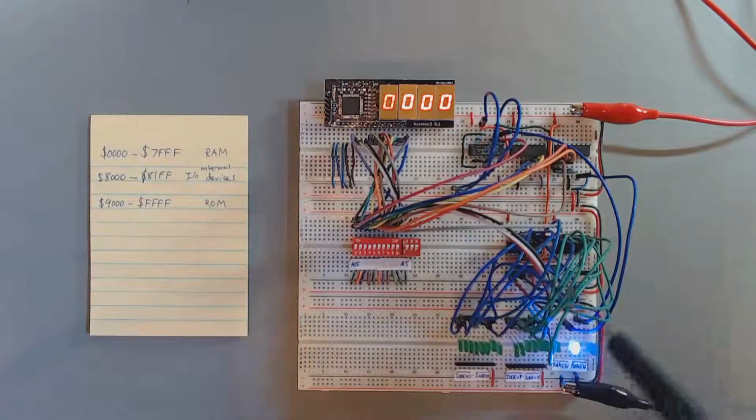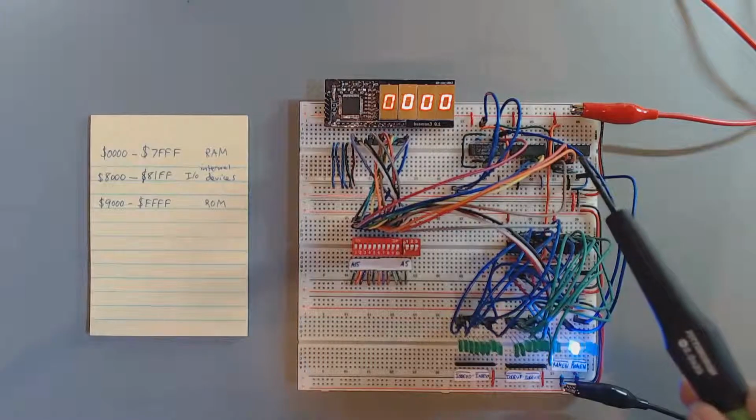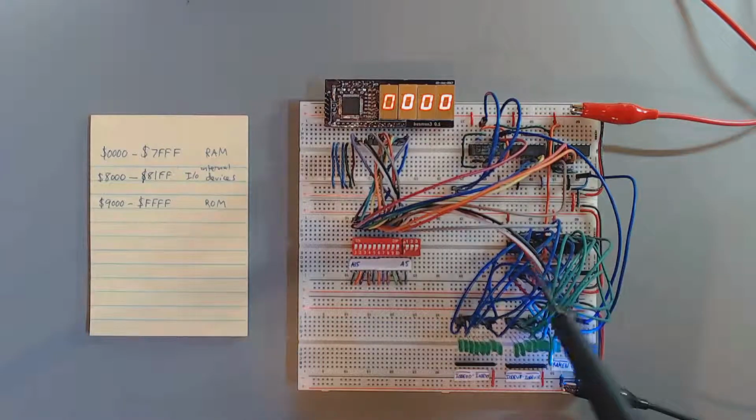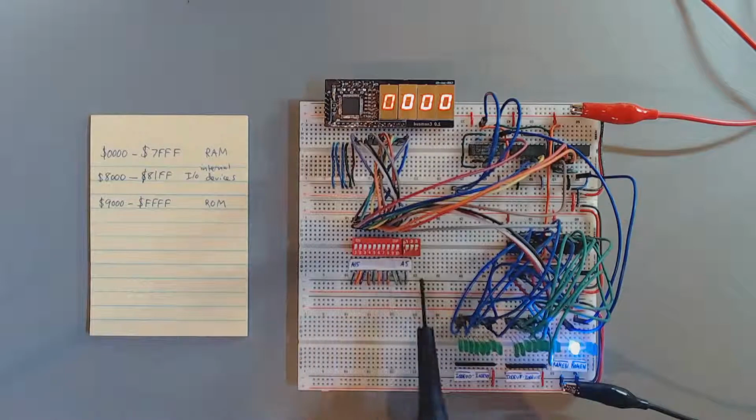All right, so here is our test circuit. These chips here are the actual glue logic. There's our NAND gates, 3-input NOR gates, the top-level 138 that decodes the overall I/O region, and then the 2 supplemental 138s that generate the individual chip enables in the first 512 bytes of the I/O region. And then the LEDs down here turn on when a chip enable signal is being generated. So right now, this is the RAM enable that is being generated. This LED represents the ROM chip enable, and then these 16 LEDs are the individual I/O device chip enables. And the 7-segment displays here show the address that we're generating using these dip switches. Essentially, the dip switches allow us to pretend to be the CPU in order to generate an address to see how the glue logic responds by enabling an appropriate chip enable signal.